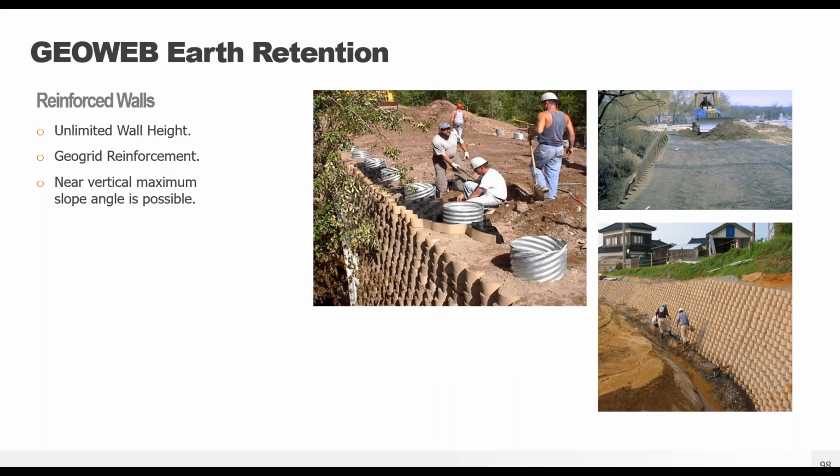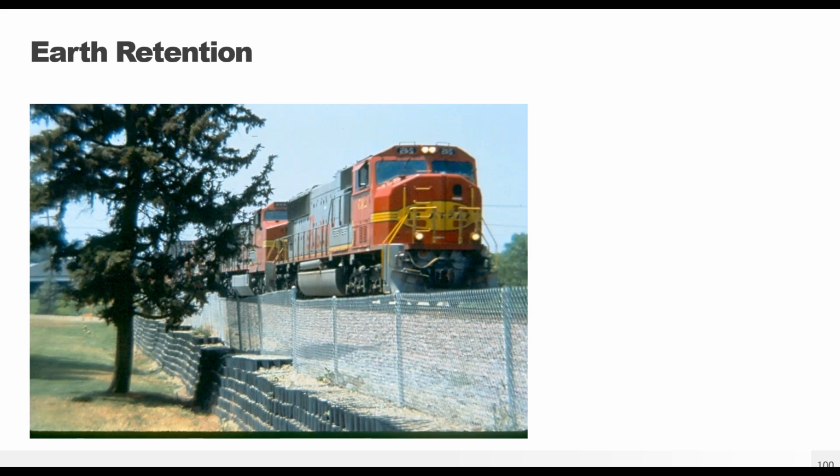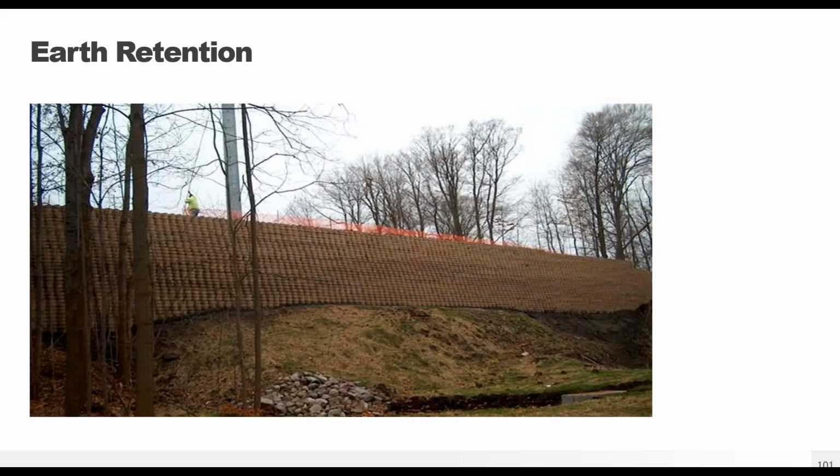Pretty much, we've done walls up to 300 plus feet high. You know, GEOB for a reinforced wall is just a fascia. We'll give you a design with all the necessary geogrid tiebacks and all the infill parameters. You can just see a reinforced wall next to a bridge abutment. You know, we do these all the time. Like I said, GEOB on the abutment can reduce the stress, but also for a wall, you can significantly reduce any kind of stress reaching that subgrade.